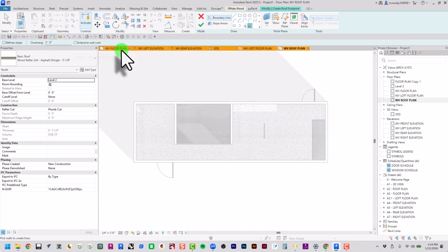Now roofs typically will have overhangs called eaves. So I'm going to click Extend to Wall Core, and my overhang is probably going to be modest. So let's go with 6 inches. If you're doing a tiny house on wheels, you're not going to have very large eaves. Like during our field trip to Roseanne's, we saw very small little eaves.